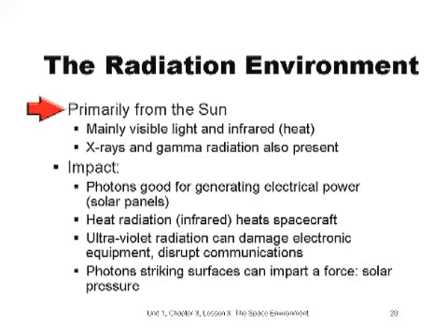We learned that the sun sends out energy across the electromagnetic spectrum in the form of radio waves to X-rays and gamma rays. Energy from the visible light of the sun is useful for satellites in generating electrical power from solar cells. Infrared wavelengths of energy striking a spacecraft can heat spacecraft surfaces. This can be a good thing if it's cold, or a bad thing if it's too hot. Certain electromagnetic wavelengths, most notably ultraviolet radiation, can damage electronic components and surfaces, including solar panels.